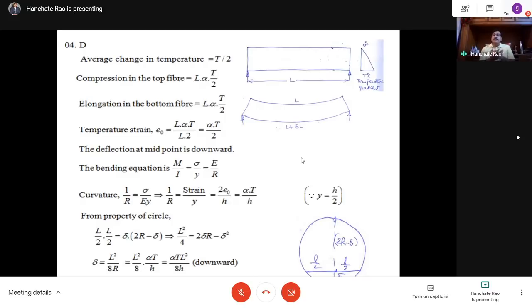The bottom of the slab will generally be at room temperature, and if you are operating air conditioning, the bottom temperature will be very low, whereas the top of the slab, which is subjected to hot sun, will have higher temperature. So actually there will be hogging, not sagging, because of the temperature distribution in a normal practical case.